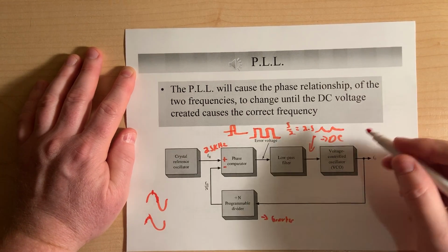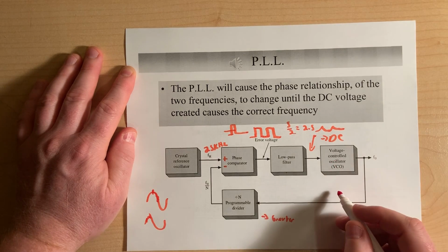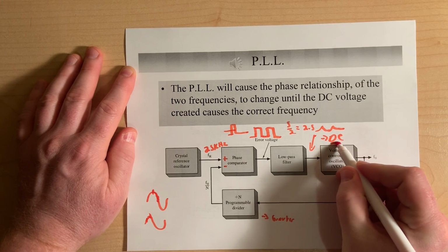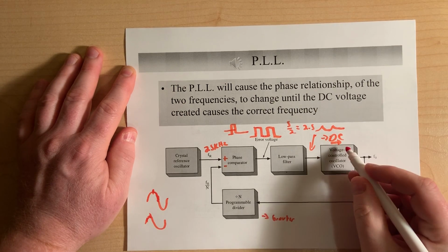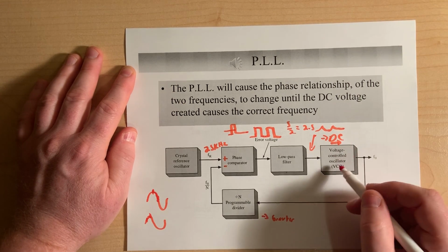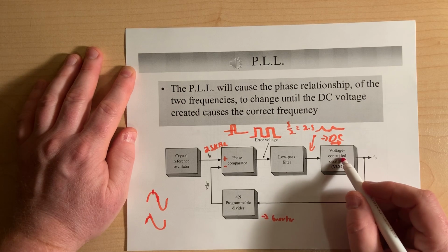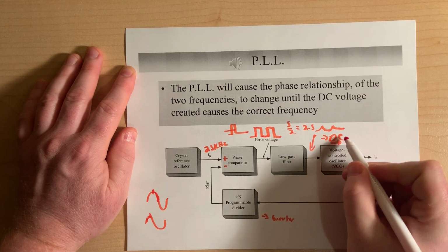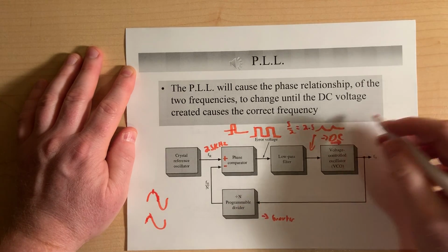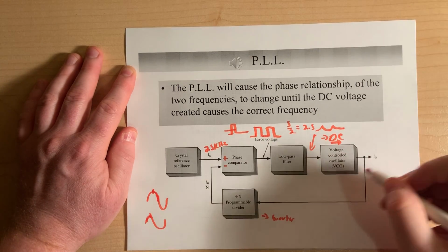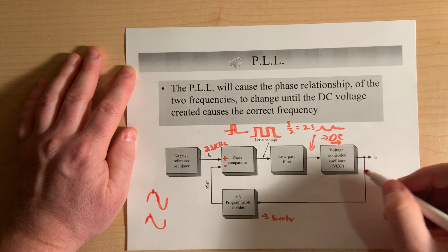Okay? So that DC value goes into a voltage-controlled oscillator. That DC value potential is what's going to change the varactor. So in the front of this voltage-controlled oscillator, remember, a voltage controlled oscillator has a potential. So this is the trigger, right? And it's got a varactor that's going to phase, right? So it's going to have a feedback path and it's going to oscillate.